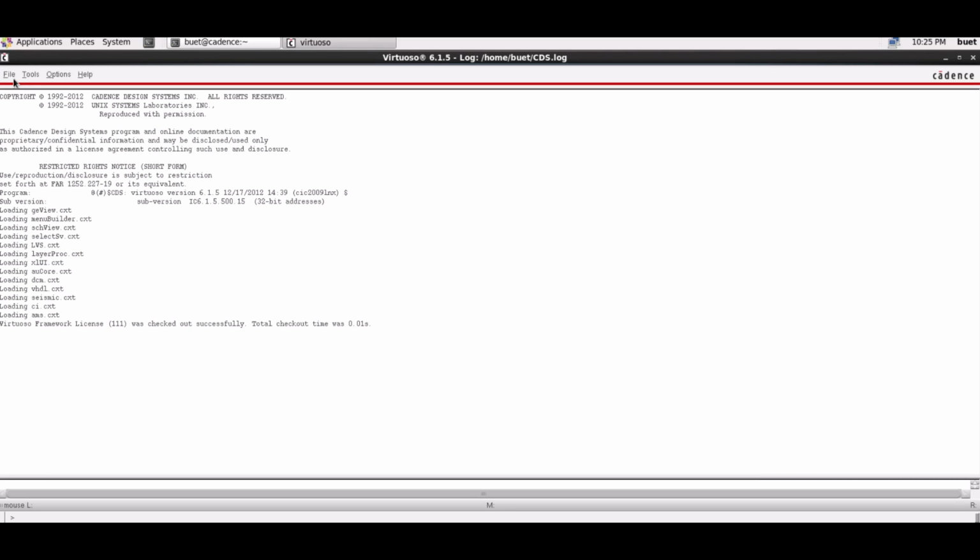Now, allowing to support all the stages of IC design and verification from a single environment, as we have just seen. These tools are completely general, supporting different fabrication technologies. When a particular technology is selected, a set of configuration and technology related files are employed for customizing the Cadence environment. This set of files is commonly referred to as Process Design Kit, which we term as PDK.